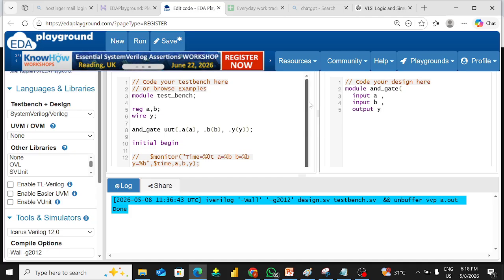Y, right? And after this, what are the inputs and outputs going to that AND gate? You need to mention that inside the parentheses, because those are the components that belong to this AND gate. And you should always remember that in Verilog code, after each line you should terminate that line using a semicolon.